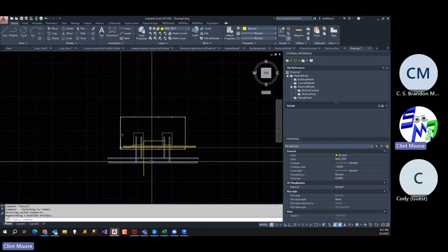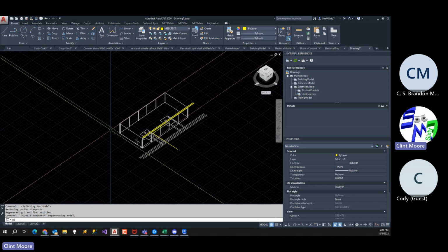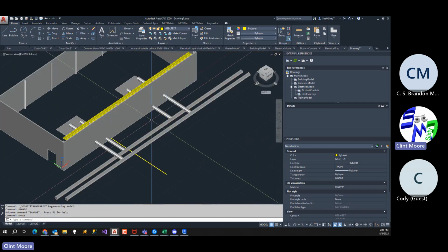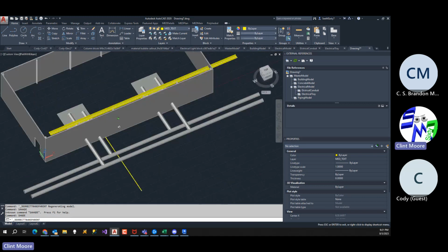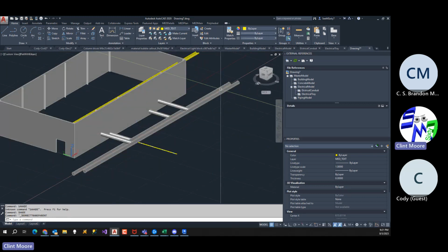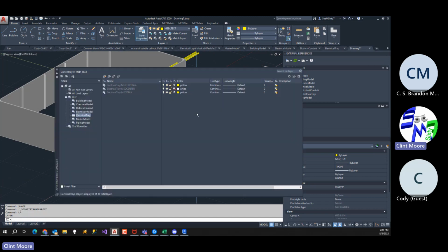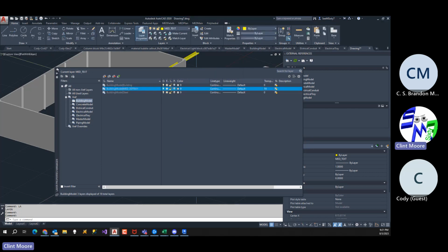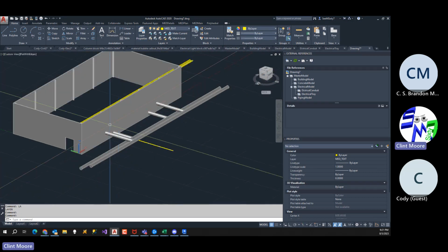If you look inside the model, if I rotate this out, I can even shade this. Boom. Oops. If you type shade, and you still see it goes to these particular colors. Yeah, we've also talked a little bit, may have talked briefly about how you can actually use transparency in your layers as well. Say you wanted to see through the building, you can click on building. Now, anything I do to the layers in here only are affected in this drawing, not in the actual model file. All right, so I go over here, transparency, click that, and I can crank that to 70%, boom, and now I'll be able to see through the building.